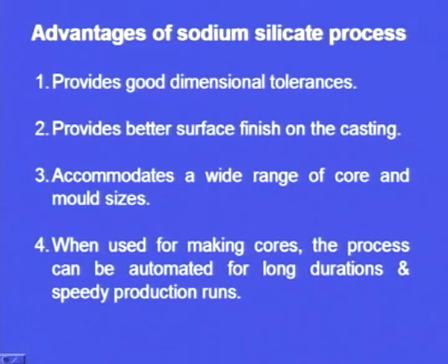Whereas a core which is made by the sodium silicate moulding process can be stored for several hours, even several days. So, if we are going to make so many castings after 2 or 3 days, now itself we can make the cores, and they can be automated.